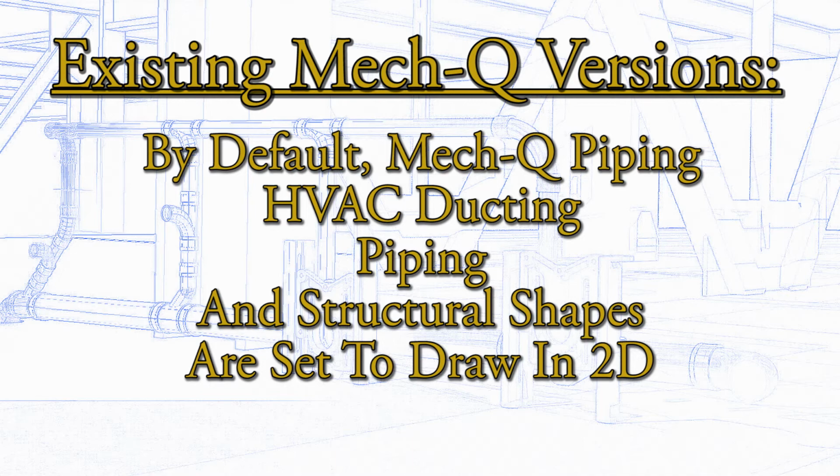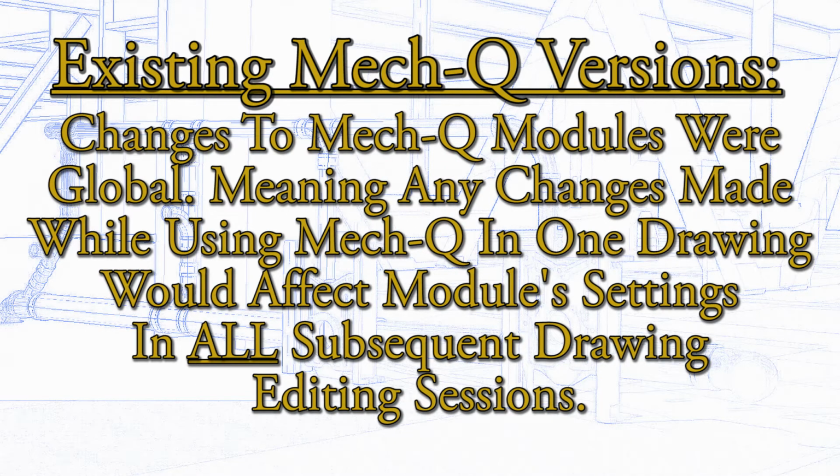Currently, when Mech-Q ships, the HVAC, structural steel shapes, and piping modules are all set to draw in 2D. In previous versions of Mech-Q, if I change these settings to 3D for these modules, all subsequent drawings would be set for 3D. But what if some of my drawings are in 2D and some are in 3D? And I don't want to keep changing the settings. This new feature is just what you've been looking for. First, let's set the HVAC, piping, and structural steel shape modules for 3D, and we'll make a few other adjustments to the HVAC and piping modules.